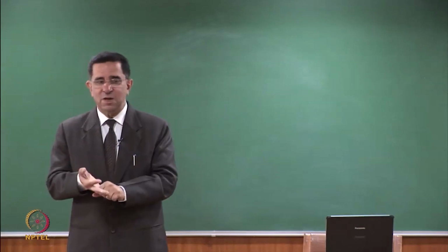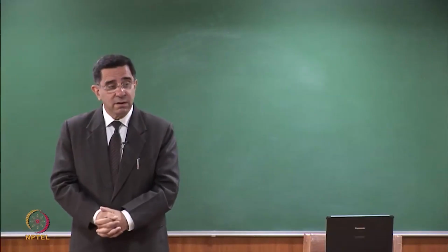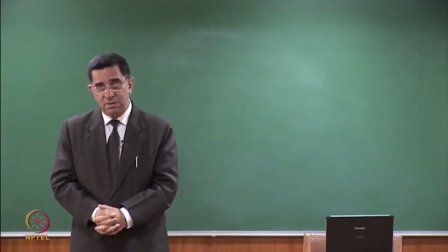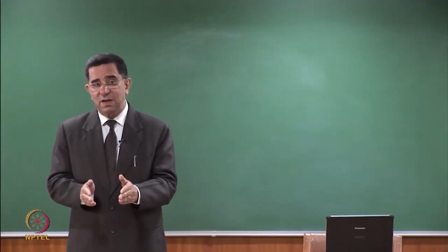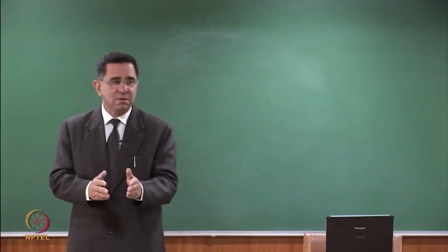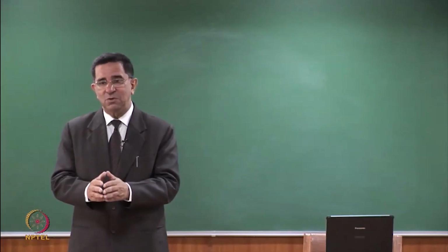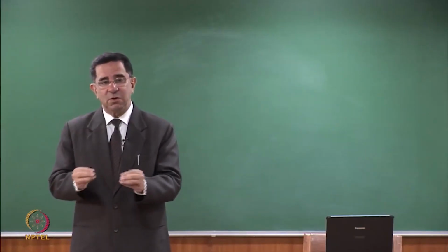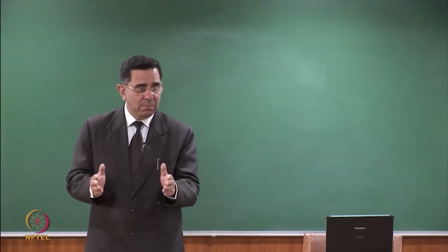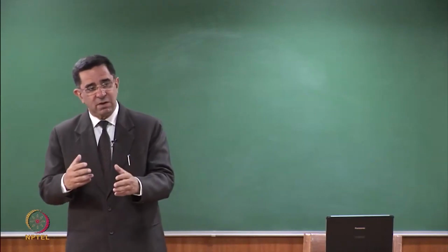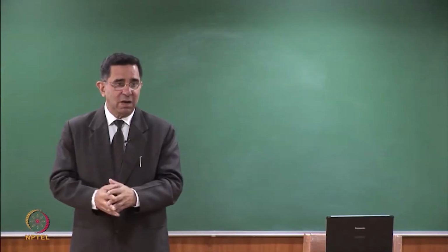One is grain size distribution, which I have already given you a rough idea. What is the next test that you do? Yes, we do Atterberg's limits. We want to know the plasticity of the material. What does plasticity of the material tell us? Well, first it will tell you whether it is plastic or non-plastic. And if it is plastic, it tells you immediately it has something which makes it interact with water in a particular way. In soils, you get plasticity because there is a net negative charge on the clay particles, and therefore the colloidal behavior, the double layer, that gives soil affinity to water, and that reflects itself as plasticity.